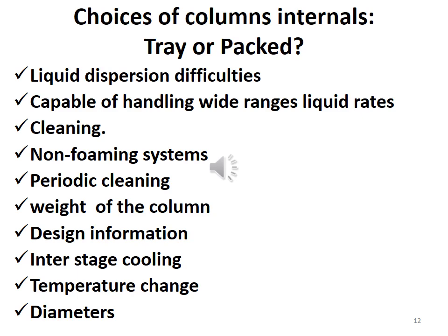So depending upon the system, we select the column internals accordingly. And the periodic cleaning, which comes under the cleaning parameter, weight of the column, design information, its dimensions, and interstage cooling, temperature change, and the diameter of the column. These are the parameters which will be taken into consideration while selecting the column internals.